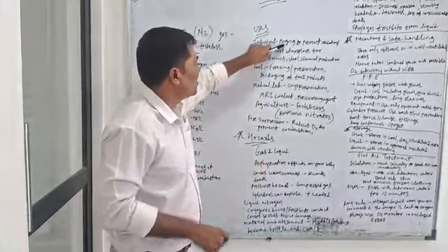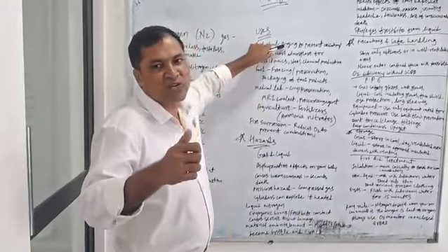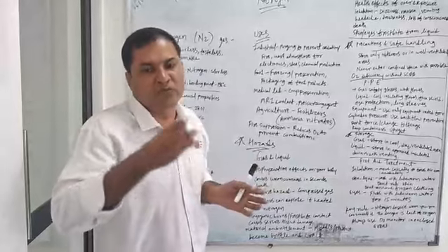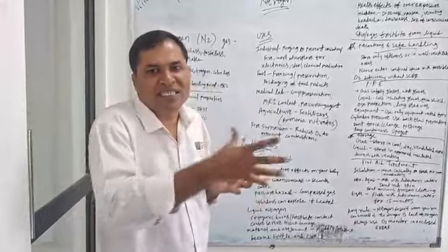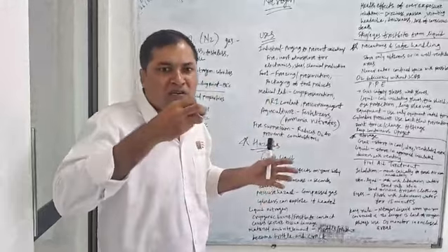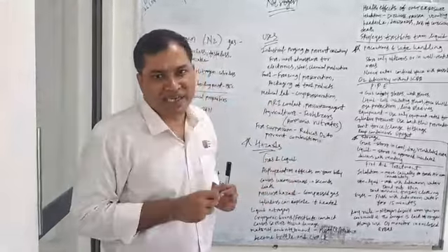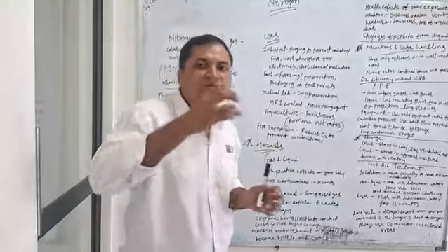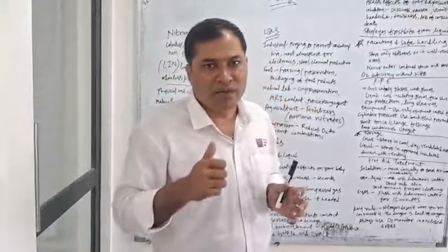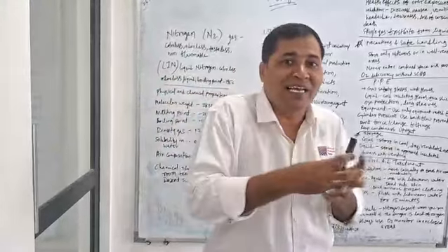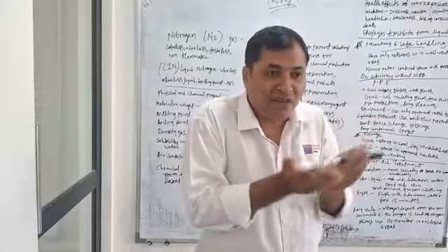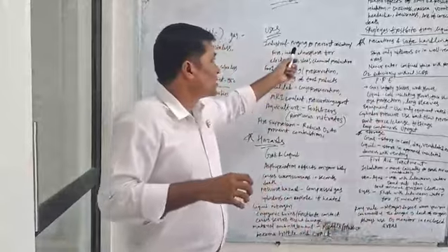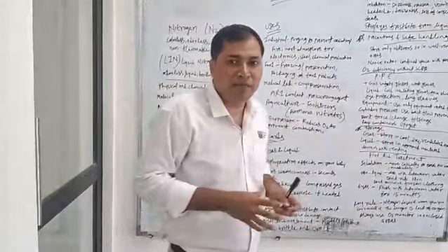For industrial use, one thing is very important. While workers are working in a pipeline, there must be no toxic fumes or toxic gases inside. So how do you send workers inside that pipeline? You need to purge it first. For purging, you need to purge that confined line with the help of nitrogen, giving the maximum pressure of nitrogen to the pipeline.